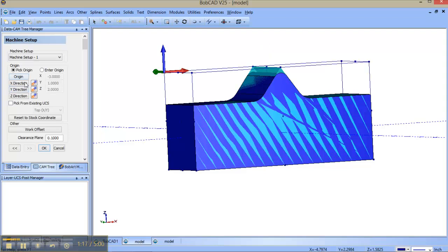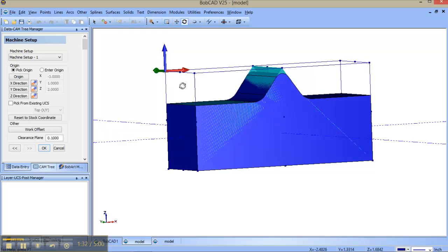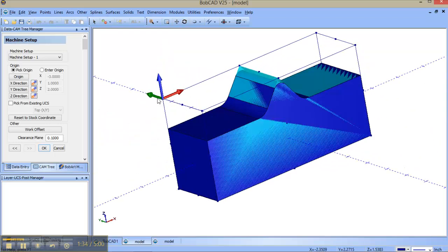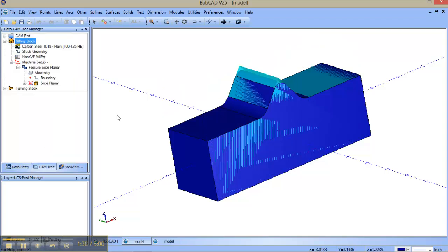This page right here is where we put our origin. What it's looking for with the STL model is going to give you wire geometry with a bunch of snap points of the overall size of your X, Y, and Z of your part file. So for this part we're in the back left corner here. Once it's all complete, we'll just click OK. What I'm going to want to do is use a slice planer. We're just going to go across this whole top part all the way across here.